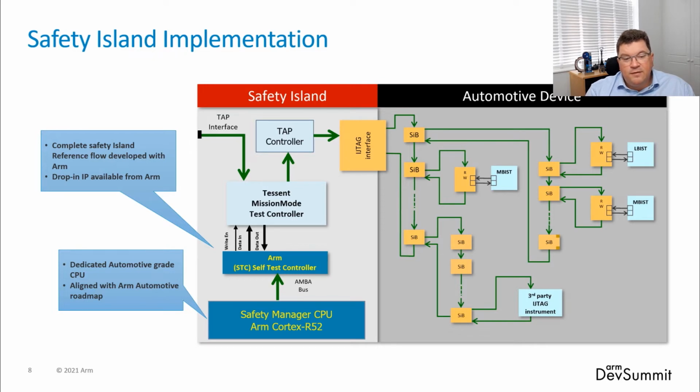And in this case, we've chosen the ARM Cortex R52, which is an automotive grade CPU, and is really designed for this type of task. So to interface the in-system test controller with the ARM CPU, we add an additional piece of IP, which is the ARM STC controller.